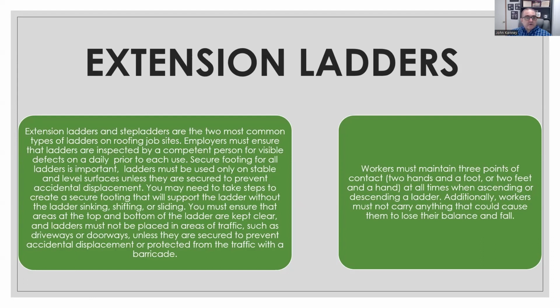You must always ensure that the areas at the top and bottom of the ladder are kept clear, and ladders must not be placed in areas of traffic such as driveways or doorways unless they are secured to prevent accidental displacement and protected from traffic with a barricade. So if there's a doorway and it is locked where it cannot be opened from the inside, and you have a barricade keeping somebody from coming in from the outside, that usually will meet the standard. But if there is any way you can avoid this simply by moving it, always do that.